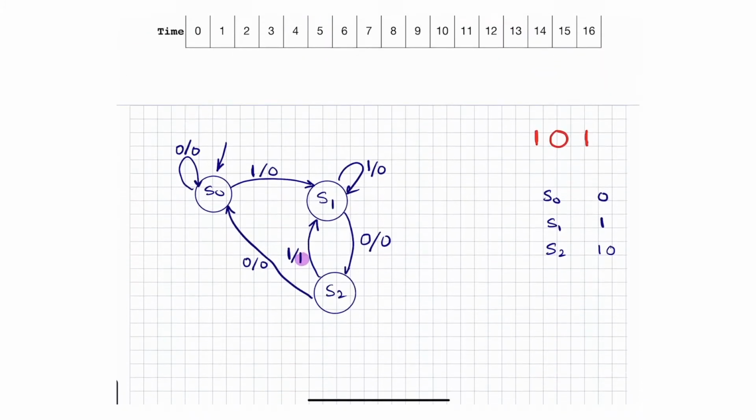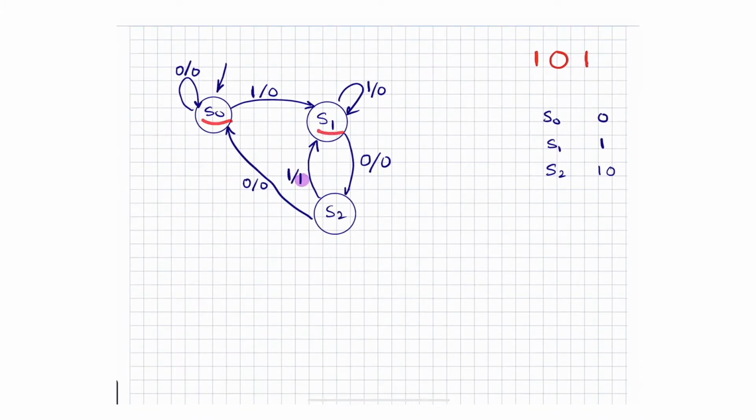So what I did in here is I actually said S0, S1, and S2. There's multiple ways of actually assigning a binary value. The easiest one is actually to assign binary values. I have three states in here, so 3 states will need at least 2 flip-flops. So I'm going to say, well, S0, I'm going to code it as 0, 0. That's a binary. S1, I'm going to code it as 0, 1. And S2, I'm going to code it as 1, 0. And of course, I'll have a 1, 1, which is unused. And I can account for that on what happens.